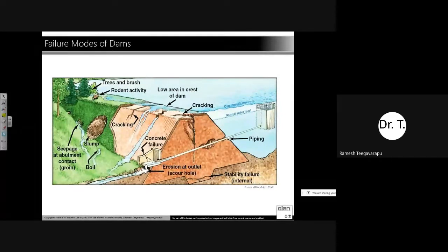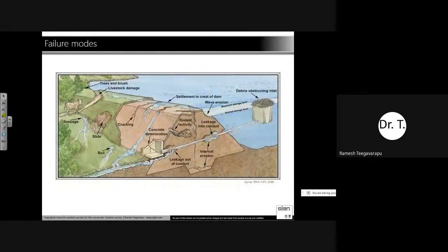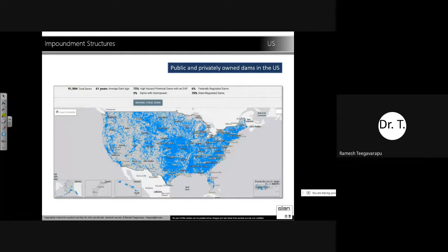And this is a result of the humidity or dry and wet cycles that cause the piping effect, or changes in the moisture content within the core as well as the soil matrix of the earthen dams. Similar evolution of different piping, piping damage through the earthen dams. And of course, this is just earthen dam failure modes, but you can have failure modes for other types also.